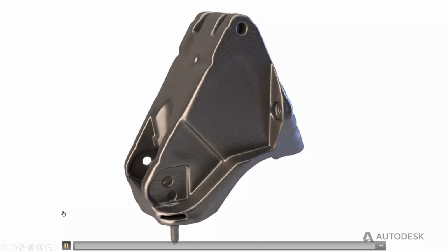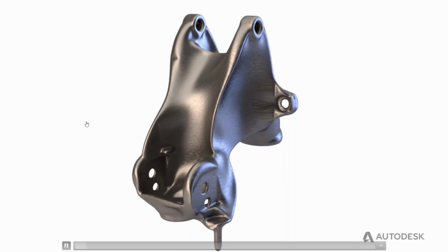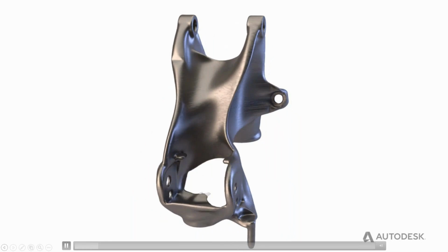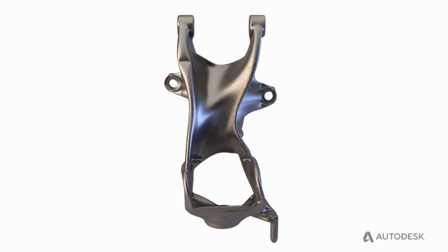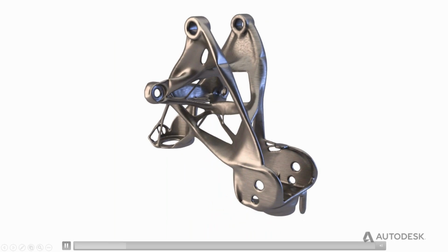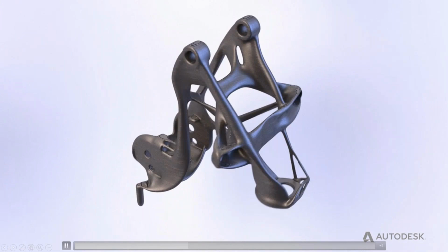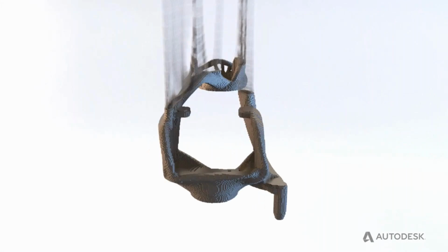So when we look at generative design today, the process is actually very straightforward. What generative design is going to do is take the entire volume that your part could fill, and it's either going to add or subtract material away from that to reach the final solve. So again, in the case of GM, this was able to provide them with a range of results that they could make trade-offs on. It could be material options, it could be manufacturing options. At the end of the day, this is allowing you to, again, make that cost versus performance trade-off.